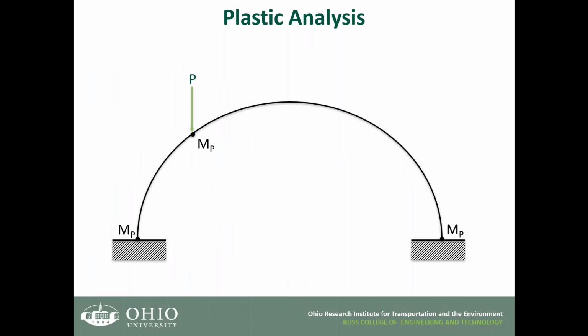And so I think, in the model that he will be using, they put an MP at a quarter of the arch and calculated the plastic moment. If somebody is interested in how you get this plastic moment, the structure is indeterminate because both supports are fixed. So how do you make it determinate? You form a plastic hinge at both supports, and then you have a plastic hinge, MP, under the load.